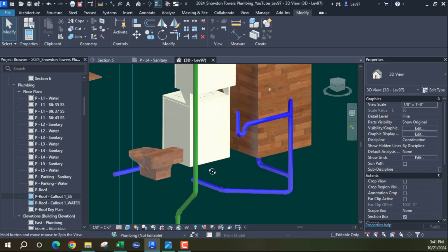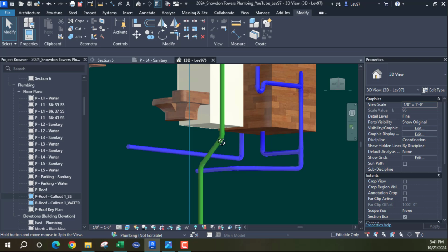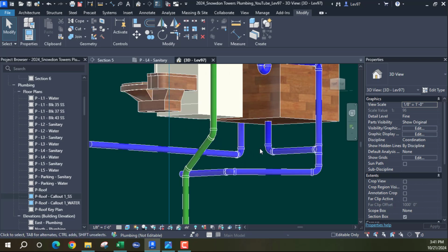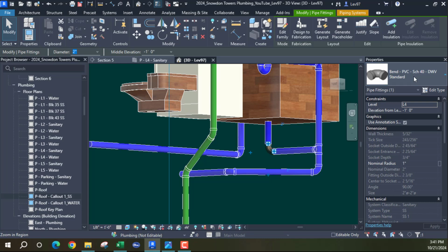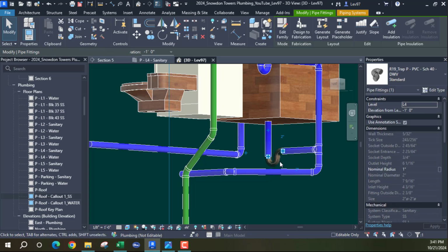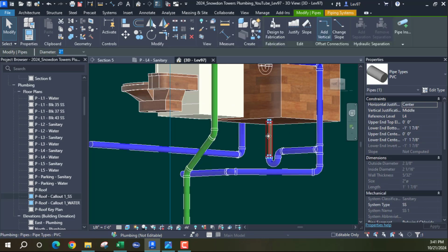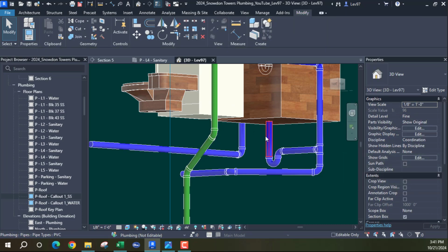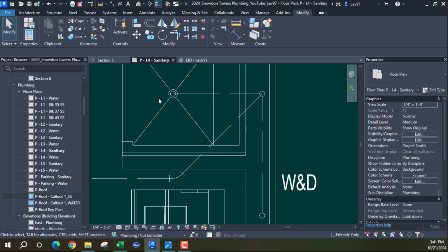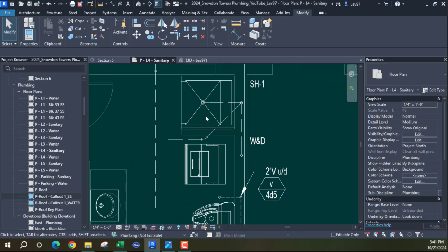So I think I'm going to stop here. And okay, this shower needs a P-trap. So we put a P-trap on. So that looks good. As long as this spool piece, this pipe piece, is less than 24 inches or 2 feet, then you're okay. And it is 1 foot. It's 13 inches. So let's go here, and everything is looking good.